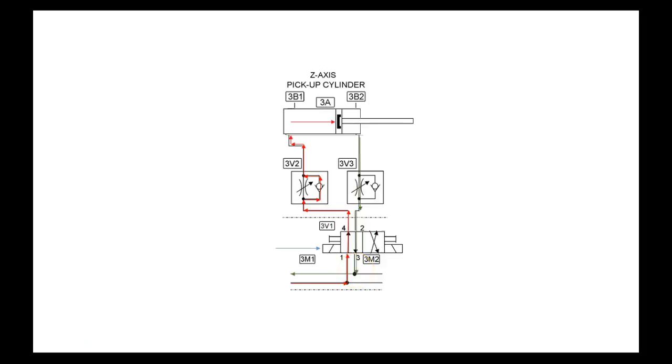So what we're doing is we're metering the exhaust. And we do that in pneumatics. Why? Because as soon as that actuator moved, the air would uncompress, and then it would have to compress again. Right? You understand? So if we metered in on a pneumatic, it would be jerky. The cylinder would be jerky.